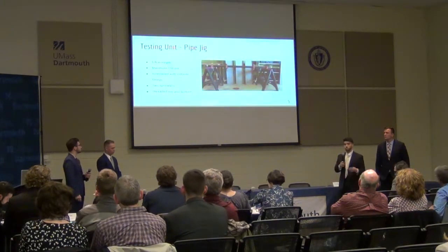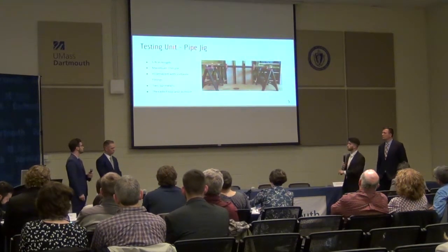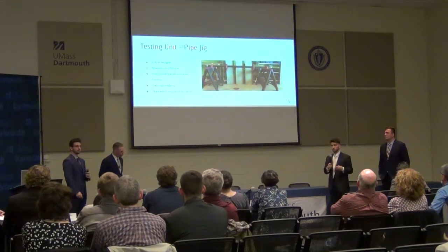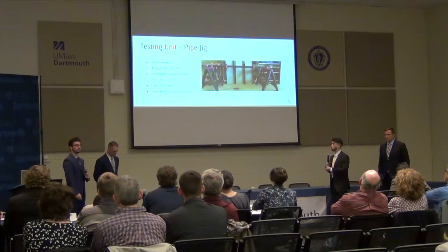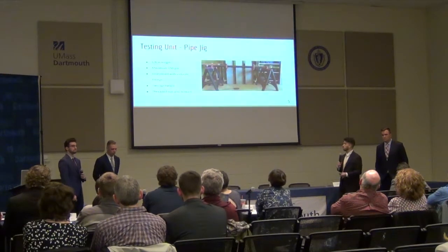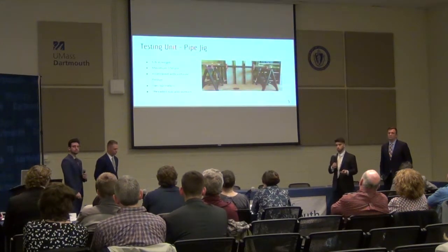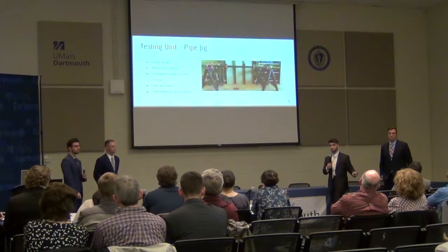As you can see, our pipe has been assembled with Victaulic fittings. The 2 Victaulic fittings that you see in the middle have threads on both the top and bottom. This gives us the ability to use 2 sprinklers at once for a test. We need to use 2 sprinklers at once so that we can ensure that there will be no false activation for a neighboring sprinkler.